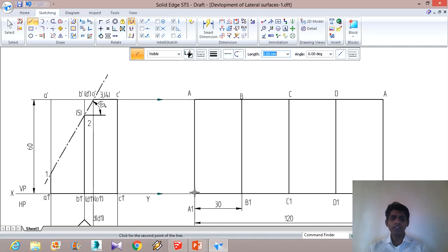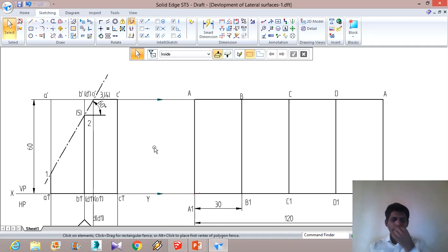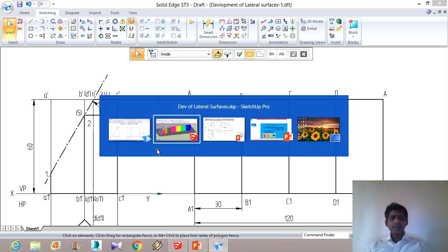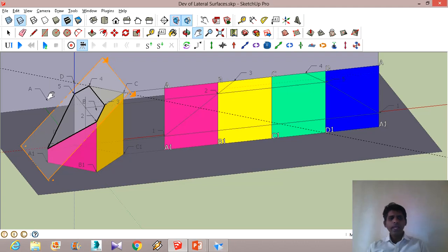So we will draw this. Okay. Now we see that AA1, from here I have to draw one line. It cuts AA1 on this particular development. So that is point 1. That is point 1, right? So all that we can do is we can draw one line from here to here, and that will be the corresponding point. Okay. Similarly, we have to draw lines from B1.